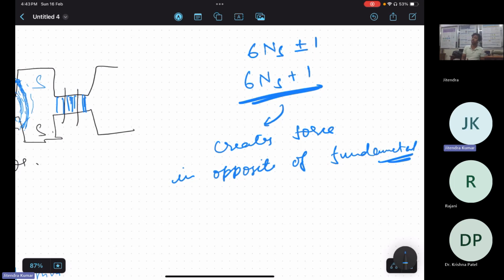And at low speed, what happens? Current is the function of slip, right? I2 is a function of slip. So at low speed, your magnetic flux is already low, but the seventh order harmonic flux is almost comparable to the fundamental. So this harmonic acts in opposition to the fundamental, and your motor starts crawling. Like it does not start rotating smoothly.